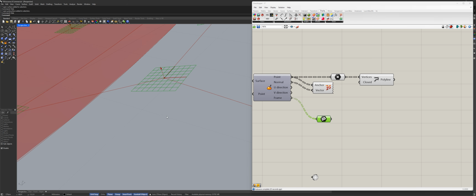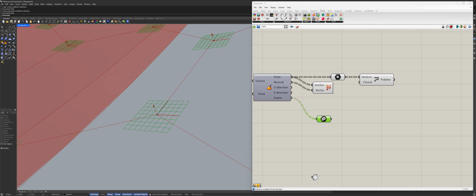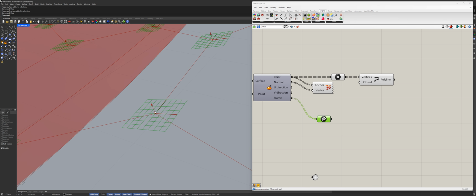Let's look at that a little bit closer. So first of all, right in the face, you have a grid. Now this grid is just for visualization. It's not real, it's fake. But there are 2 very important elements here, the red line and the green line. And I believe you already guessed, they are the axes of your plane, axes of a local Cartesian coordinate space. This is x, this is y, and there's supposed to be a z. It's never drawn, but it's there, right? Instead here for the z, you see our normal vectors, right?